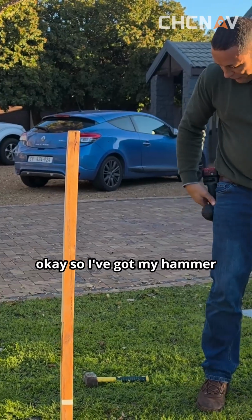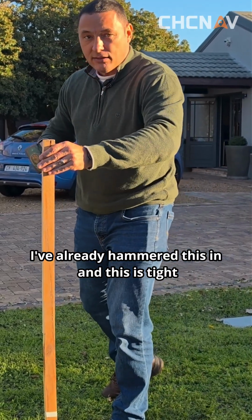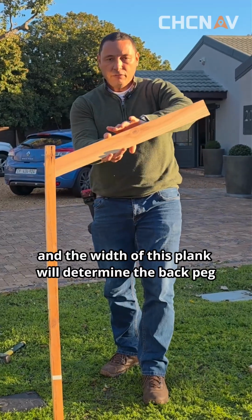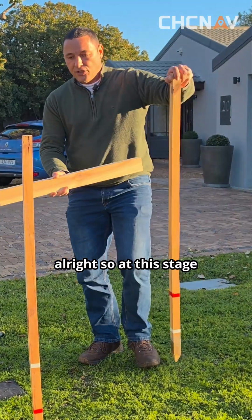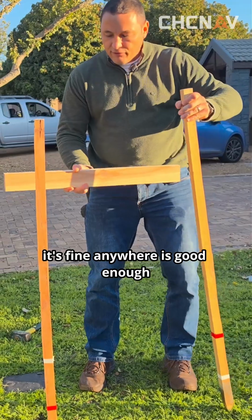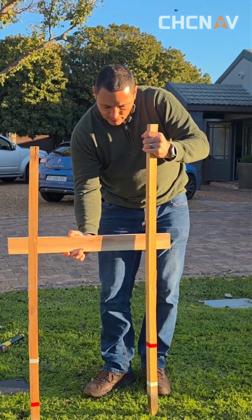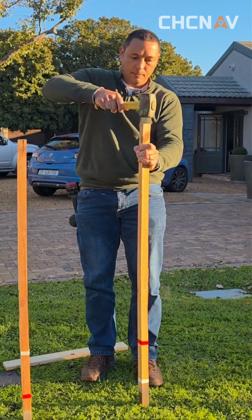Alright? Okay, so I've got my hammer. I've already hammered this in, and this is tight, not like we have it here. Okay? I take my batter plank, and the width of this plank will determine the back peg. Alright? So at this stage, it can be anywhere that you want to put it. It's fine. Anywhere is good enough. Just try to get it more or less perpendicular to the road direction. So I have it sort of like that. And this is where I'm gonna now put in my back stake.